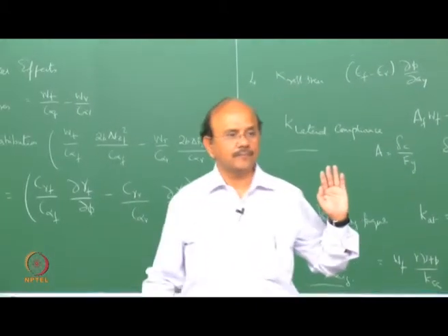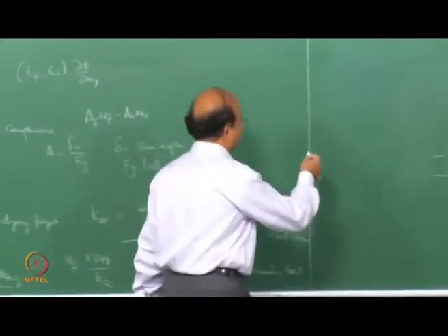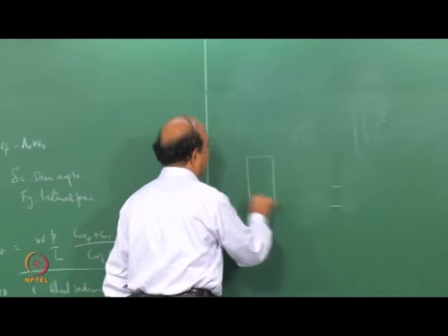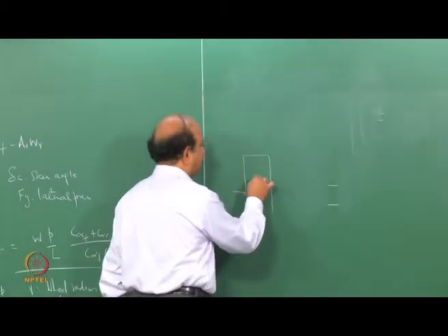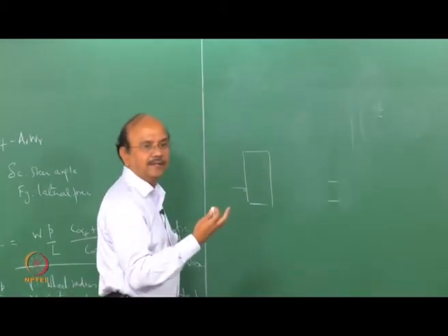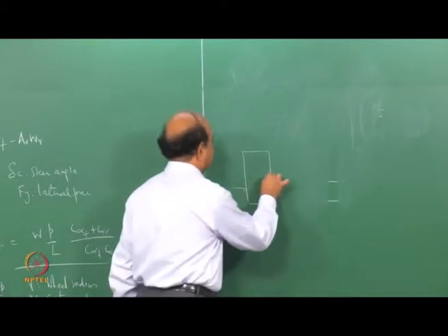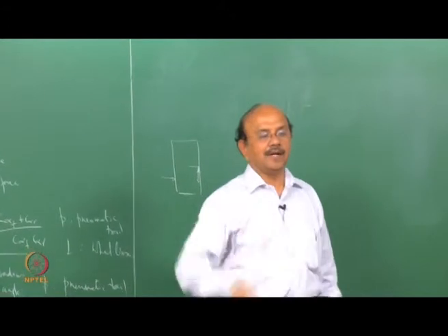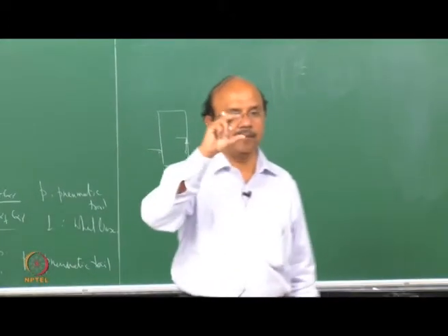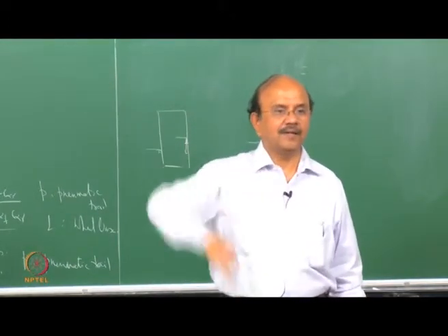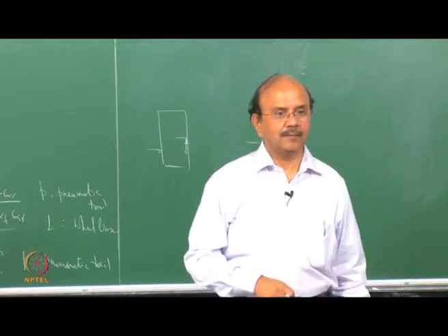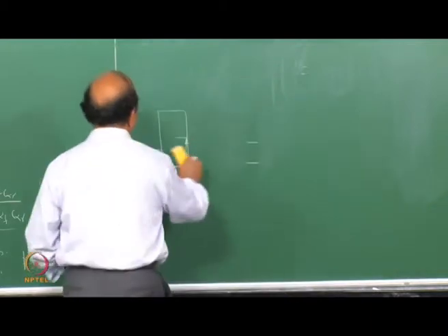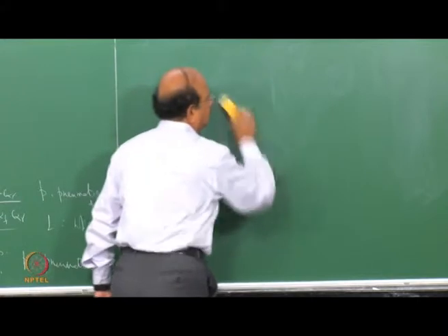Any questions? Yes. Pneumatic trail? Pneumatic trail, we already saw that. The lateral force does not act at the center, it acts at the rear. That is the moment that's created, the distance at which this force acts and gives the aligning torque. The force multiplied by pneumatic trail gives the aligning torque. So that's what we saw long ago as the pneumatic trail.